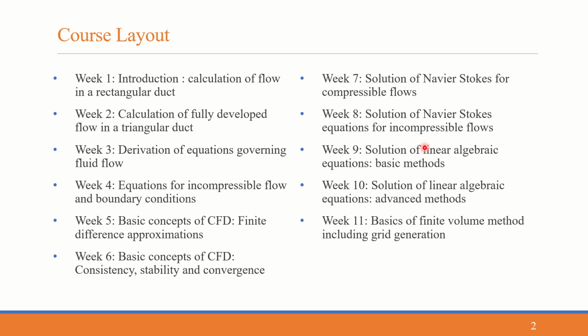In structured grid, you need to be consciously aware of changing the grid density at one position when you are changing it in another position. The change in one position will indirectly affect the other position also, which you need not worry about when you're talking about unstructured grids. So there are pros and cons of each technique. It finally comes to what your requirement is and what you're willing to sacrifice. So those things matter. And grid generation and finite volume method.